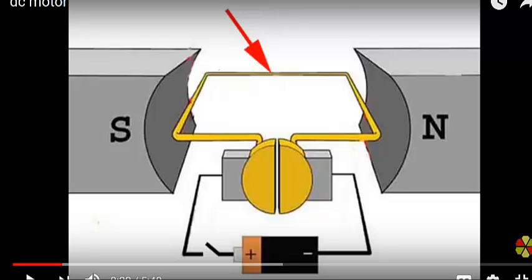And you have this split ring. What happens in this case is, if you flip the switch, the current will go through this wire into this half of the armature up to the wire, and then the current will flow through the wire, and because of the force on a current carrying conductor, there will be a force. Actually, the force will end up being both here and here. But the force here will be into the board and this one will be towards us, and they don't create any torque. Let me continue on, because I'll show that in a second.